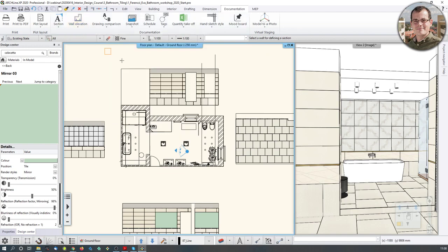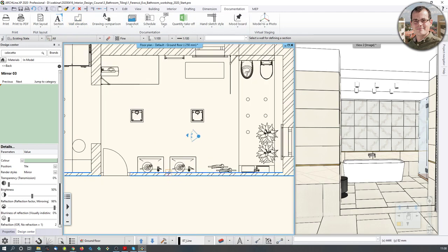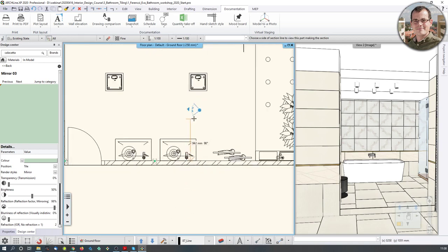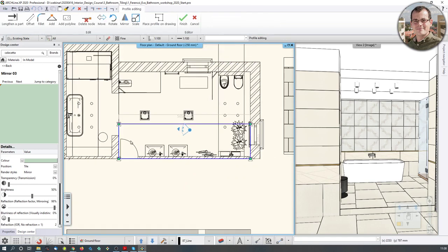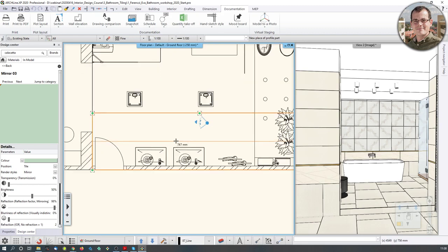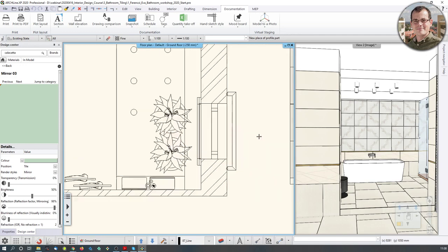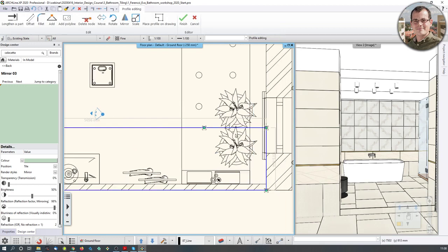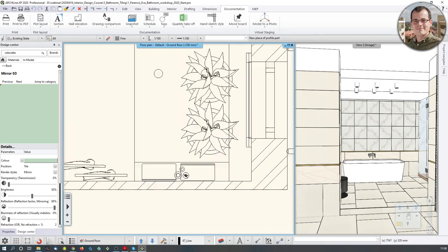We are going to go with image, and click on the wall that you want to get a wall view of. So just click on the wall, and now the software tells you which direction you want to look at it from. I don't know if you see this orange arrow, but you make sure it's pointing from where you are to what you want to see, like that. And then define the width of what you want to see, and the depth. Depth is always good to trim back a bit, because otherwise, for example, I don't want the second plan to be in there. I just want to have the first one. Or if you are inserting a node, then even the second one could be ignored like that. So I don't want to have this very nice plant over here.